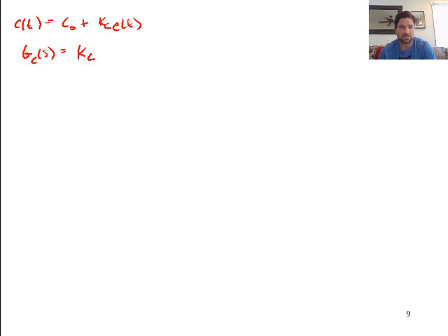We're going to look at a system where, in this case, we apply it to a first order process. So we'll say the process is Kp over tau ps plus 1. Here, we're just going to say a fast actuator and a fast sensor, so we set these equal to 1. Here we're just trying to take a general process and look at the effect of the P-only controller on the overall process response.